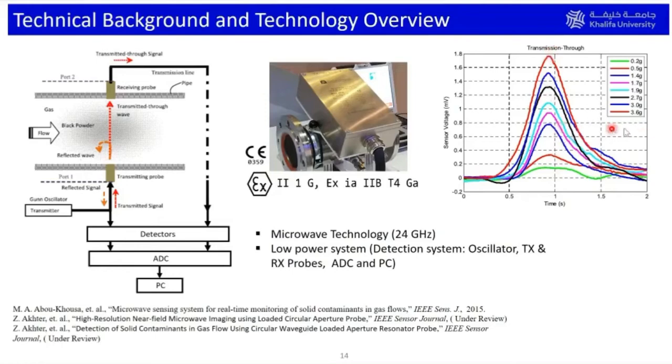So we can see this is a very good measurable signal, and this is also a very good measurable signal, although this one is debatable. So we can consider this signal as measurable with this hardware. This is basically 0.5 grams per 2 seconds. So if 0.2 grams of the black powder is flowing inside a pipeline, we can detect it through this electronics. This was our previous achievement.